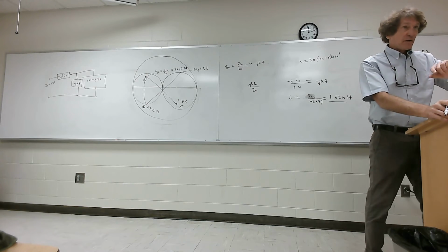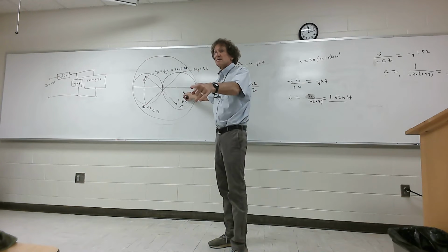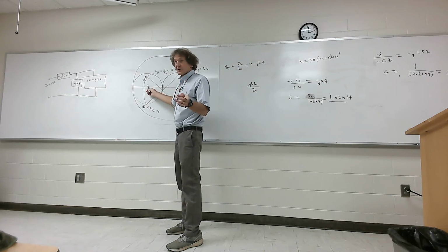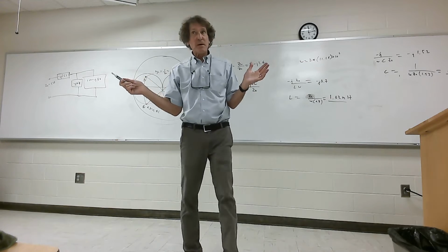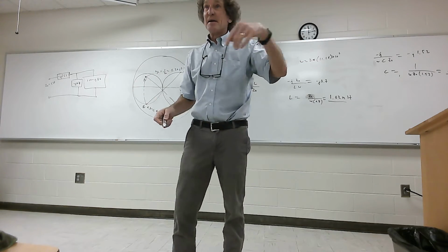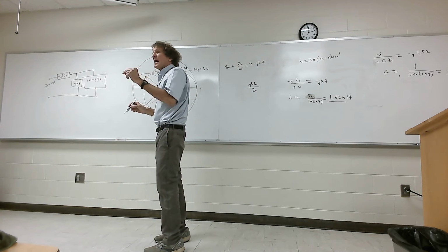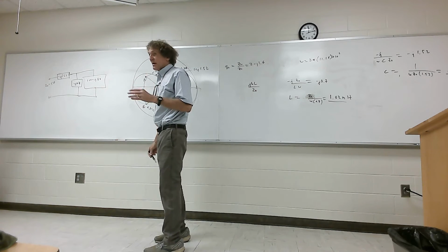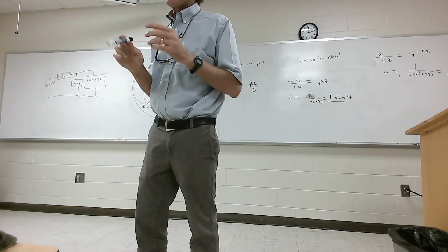All right, remember, one last thing. If you're inside the normalized impedance circle, the one circle, you've got to go to the admittance domain. First element is in parallel. If you're inside the rotated circle, first element is in series, right? It's an impedance. If you're outside of both, it doesn't matter. The only thing you got to remember is what you're doing. If you're in the impedance domain, out here, and you want to move to here, that's going to be a minus J you're adding. Follow me? If you're down here and you want to move this way, it's a plus J. So you have to keep your head on straight about whether you're moving with impedance or admittance, and that's the only thing I'm going to tell you.